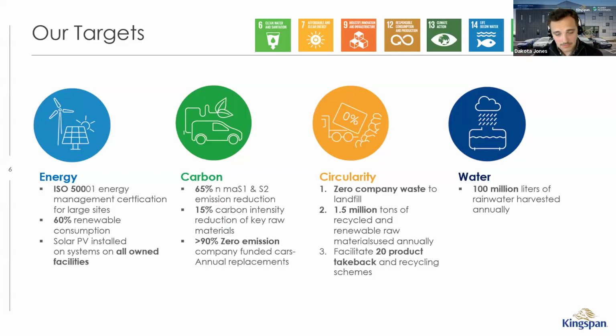The insulation of our panels that we're going to be talking about today, you'll notice it's this distinctly gray color. And the reason for that is because it's a proprietary hybrid blend of polyisocyanurate. And the reason it's gray is because it's 11% recycled post-consumer plastic, meaning that we're actually taking plastic out of the environment and putting it in our building products. At the end of the building's life, when these buildings are being dismantled and there's no longer a need for IMPs, we actually have a take-back program where we can take the panels back, mulch the insulation on the inside, put it in concrete as aggregate to make it lighter weight, heavier insulation value, and then the steel is recycled entirely as well, thus eliminating even more potential carbon from getting in.